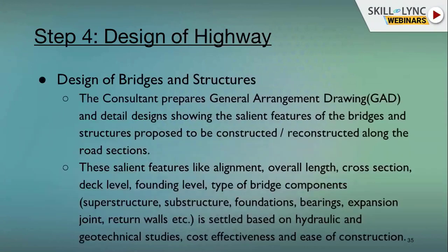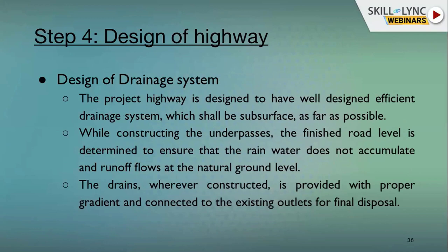Design of highway also covers structures. In structures, I'll not detail it much here. This also depends initially on the alignment, how the alignment will come. If it is a major structure, this major structure will guide the alignment. The GAD, general alignment drawing, is to be prepared, and based on subsoil data, structural design has to be done.